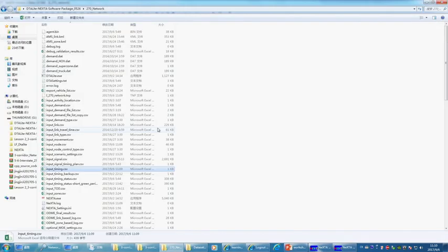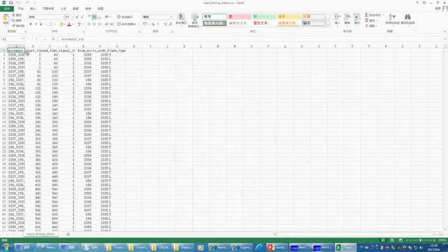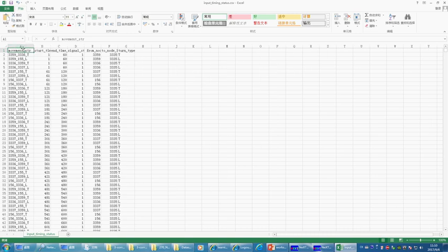Okay. The user can further run the executable of timing generator here, timing generator, to provide input timing status file in this format. Let's try to open up this input timing status file. So in the input timing status file, we have movement string, starting time in seconds, ending time in seconds, signal status, from node ID, to node ID, and a turn type.